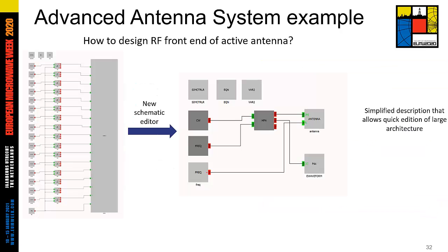Now, thanks to the power amplifier model and antenna model, we can start to design our system in a system modeler. Vision System Modeler is a simulation environment that includes a schematic editor in which we can connect our PA model to the antenna model. In this example, we address a 4x4 phased array antenna. So we must connect 16 PAs to the 16 ports of the antenna model.